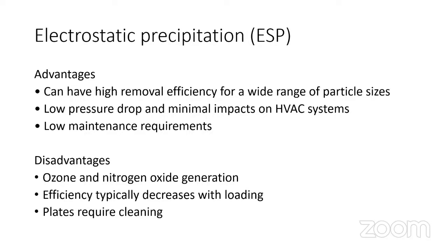So you would have to have some kind of a filtration method further to the ESP to reduce such gases. And here the efficiency decreases with the loading, because as there is more and more deposition of particles on the plates, the ESP charging would be affected, and so it'll basically reduce the efficiency. So plates would have to be cleaned at regular intervals.